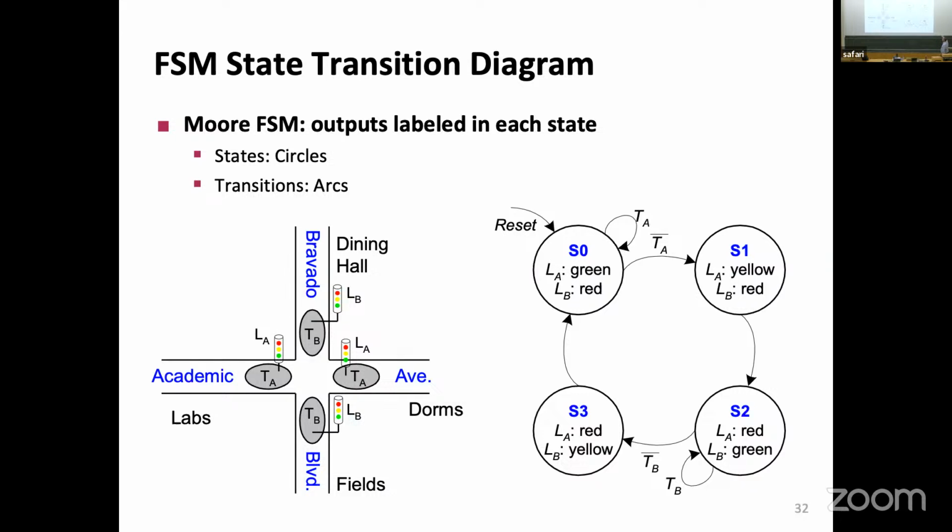And we stay there as long as there is traffic on B. And if there is no traffic, now B turns yellow, A is still red, and then we move to the phase where B is red, A is green, and this can go on forever. I have 4 states. It has a finite number of states, 1, 2, 3, 4, right? And that's a finite state machine. We solved the traffic problem of this utopian city.